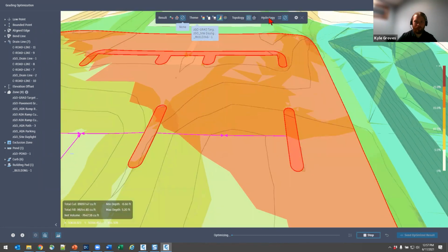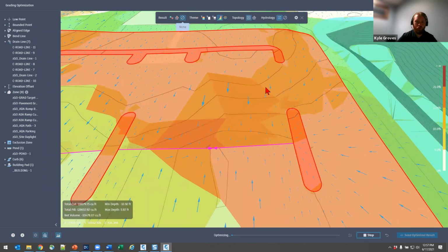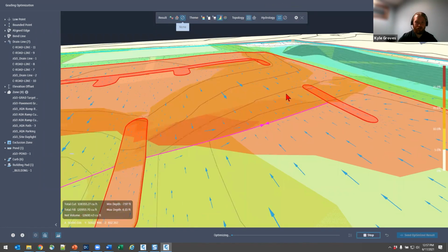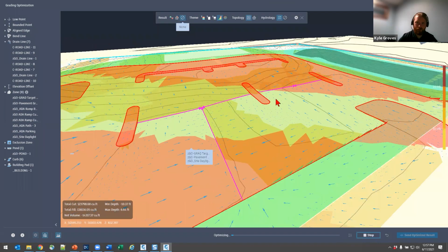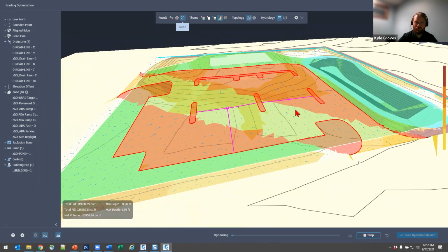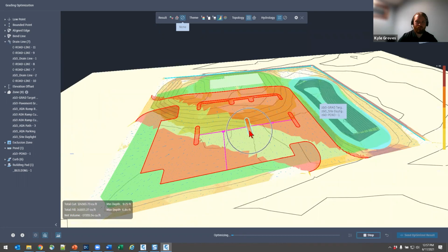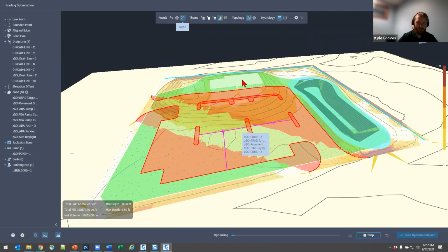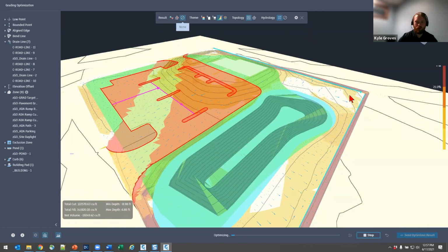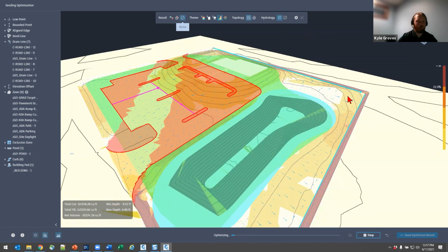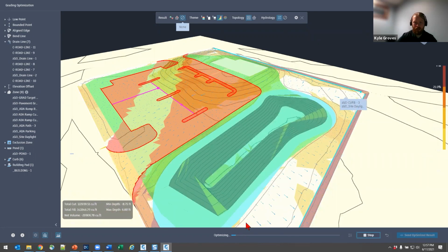Another one that you're probably interested in is your hydrology slope arrows. That's going to tell you where your triangles are sloping to help figure out how that's all going. Now, if I zoom out far enough, we can see my basin was pretty easy for it to get through. It made my curbs for me really quick. It seems to be trying to pick up my building elevation. And in this northeast corner, that's where it's going to put a berm for me for a lot of the site balance that I'm looking at.